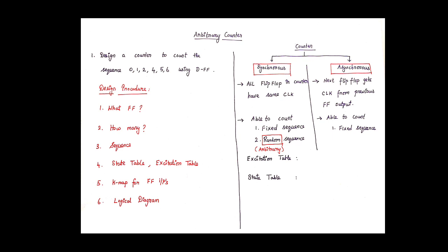What is the design procedure for the synchronous counter? First step, we are going to design a counter, that means it is going to have a group of flip-flops. What type of flip-flop? Second, how many flip-flops are needed? The total number of flip-flops tells how many counts and how many different states are possible. So, what type of flip-flop, then how many flip-flops are needed.